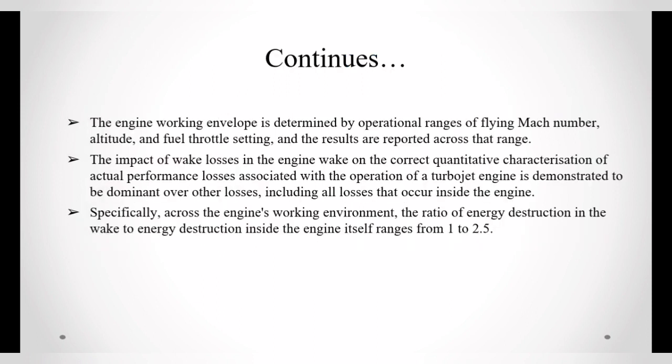Continues. The engine working envelope is determined by operational ranges of flying Mach number, altitude, and fuel throttle setting, and the results are reported across that range. The impact of wake losses in the engine wake on the corrective quantitative characterization of actual performance losses associated with the operation of a turbojet engine is demonstrated to be dominant over other losses, including all losses that occur inside the engine, specifically across the engine's working envelope.